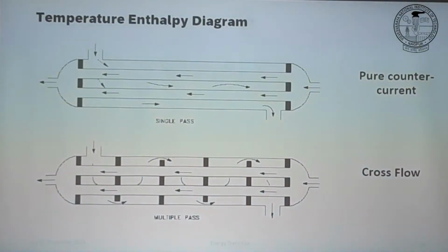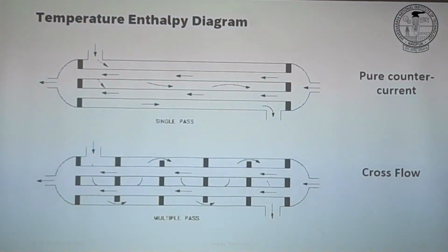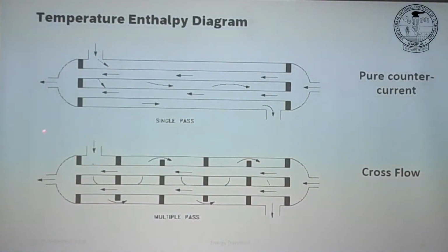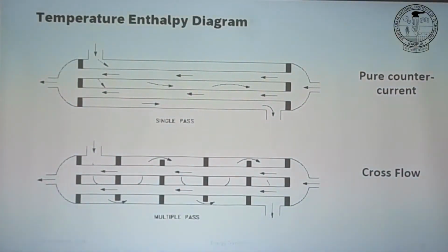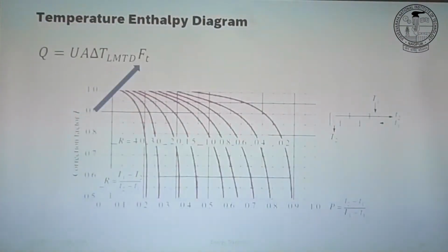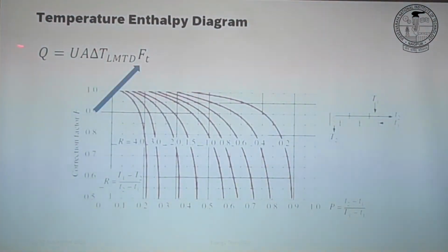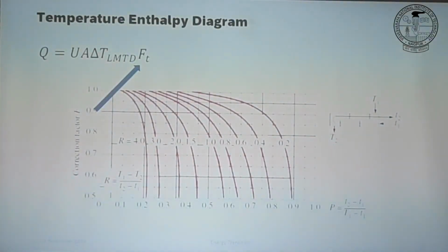Mixed temperature difference. Okay. And ideally, if you want to do a real, detailed calculation, you split it into different zones and do your calculation based on LMTD co-current, LMTD counter current, LMTD cross. But in reality, what you do, you calculate LMTD based on counter current and update it with a factor called FT, the correction factor, which is always lower than 1.